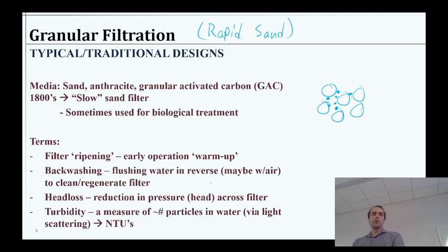Okay, head loss is another term. Essentially, when we add water to these filters, as they fill up with particles and get junked up, then it's going to require a little more pressure to push water through it, because essentially these pores that water is traveling through are getting smaller and smaller because they're filling up with particles. So we have to apply more pressure, and typically for a granular media bed like that, we're going to apply more pressure just simply by letting the water stack up a little higher. So we're getting more height of the water, so that means more force from gravity pushing through.